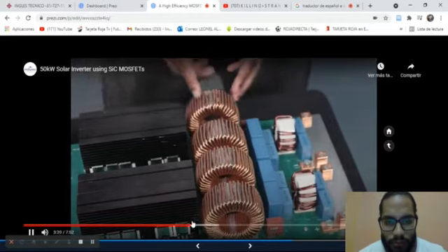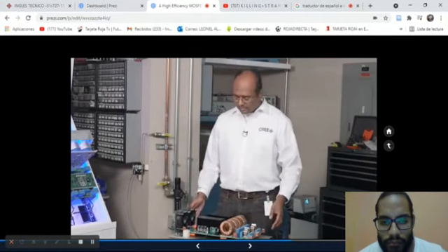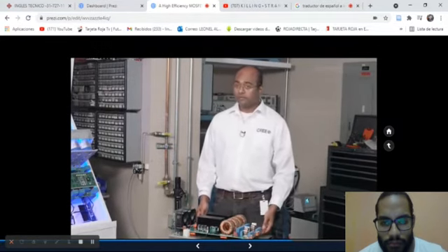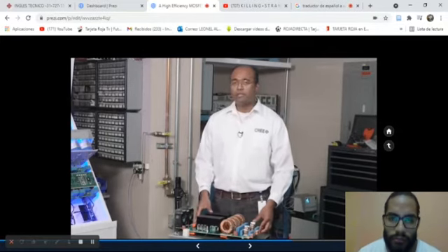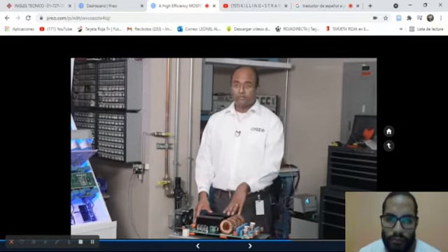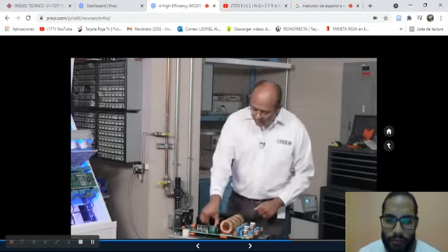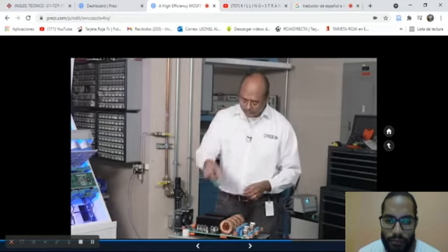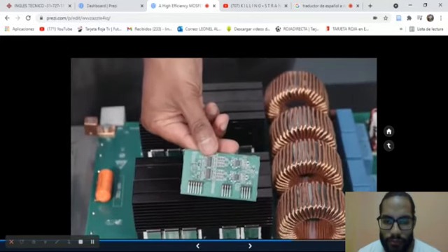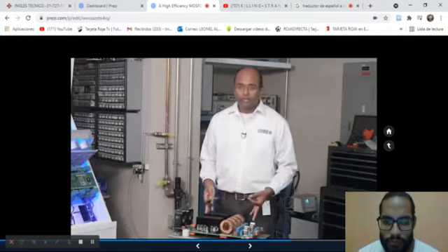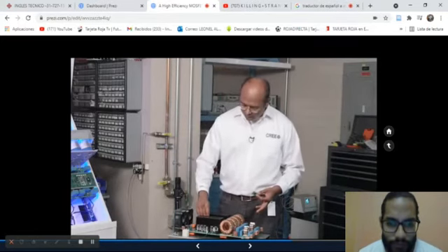Interleaved phase legs. Each phase leg is switching at 75 kilohertz. And what you'd notice is that the entire system, the whole 50 kilowatt system, fits on a single board. The board by itself weighs 7 kilos, and that includes the magnetics, the heat sinks, the power switching devices, the gate drivers. We have little daughter boards that are the gate drives. We also have little daughter boards for the control card. This is an analog controller. Our purpose was to show the power density and the power to weight ratio rather than advanced control schemes.